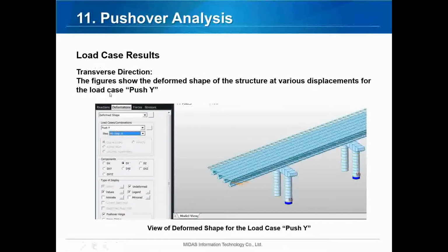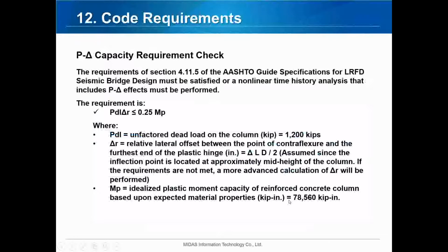So again, in the transverse direction, we did a similar analysis, and that was for push Y, and we looked at the displacements in the Y direction, and the location again was right at the bottom of the columns, which is where we started forming plastic hinges.